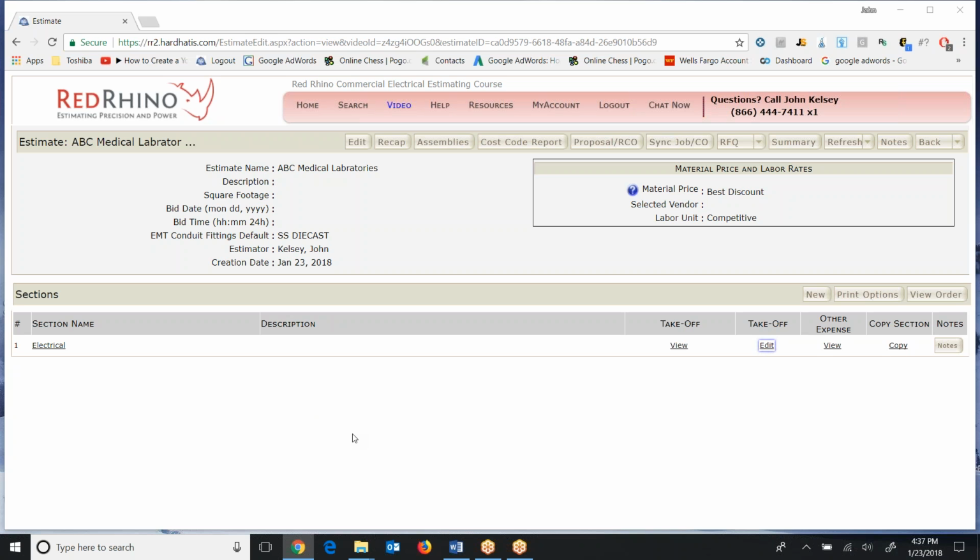But let me explain. Again, the purpose next is you would make a material list and you would input the materials into that section. Now, if you have multiple sections, you have to make different material lists and input the materials into each section. Over at the right next, if I was done or just using one section, I would click Take Off Edit. Let me show you some more examples for sections to give you food for thought.